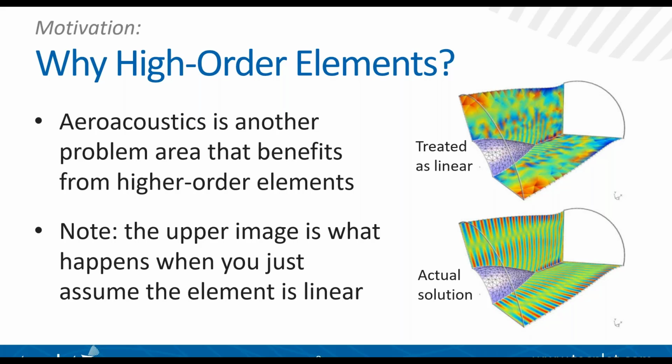The image on the upper right shows what happens if you treated the elements as linear by throwing away the extra nodes for the purpose of visualization. So it's the same solution, but you've just thrown away the extra nodes and used it in a visualization code like Tecplot. And you can see that it doesn't really represent the true solution.